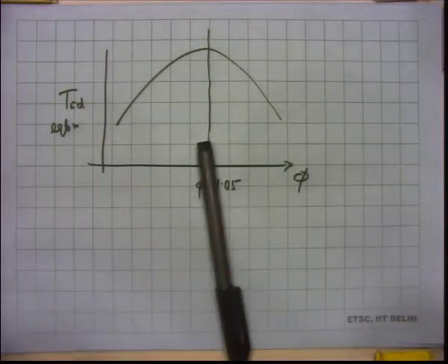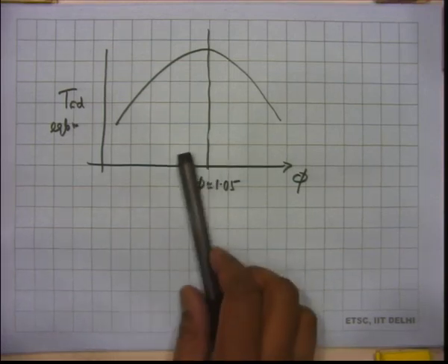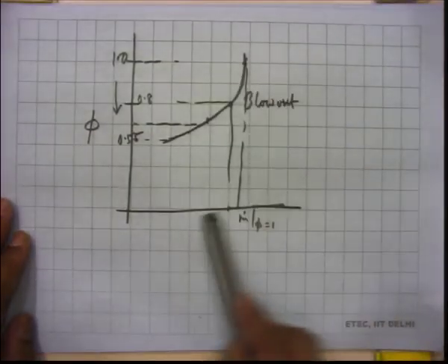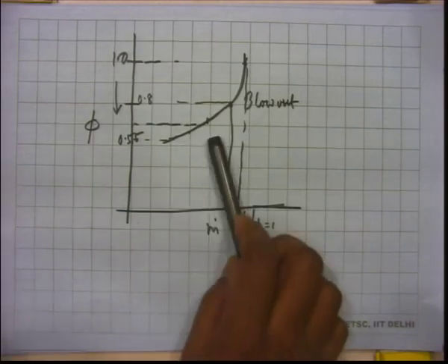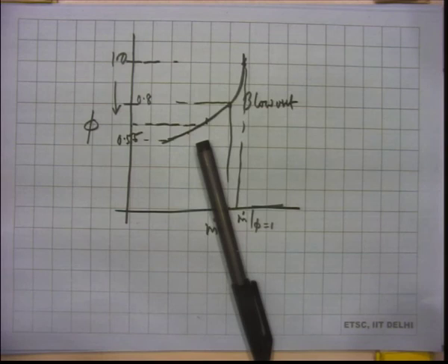So, if you give the right amount, the chemically correct amount of air for the fuel concentration that you have, you get higher temperatures, which means that the reaction is good. So, it is a strong flame. If it is a strong flame, it is not going to blow out that easily. Okay. So, you need a higher value of m dot. If you do a lean mixture, it is very delicate, because it has got too much air, too little fuel, the reaction is weak, the adiabatic flame temperature is low, so it is a weak flame.